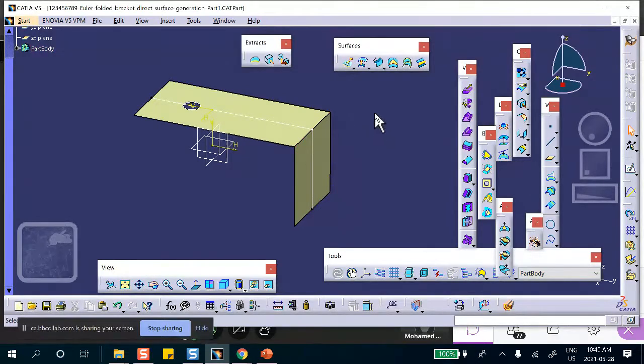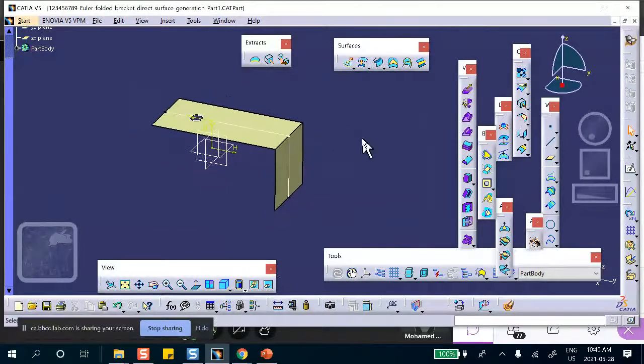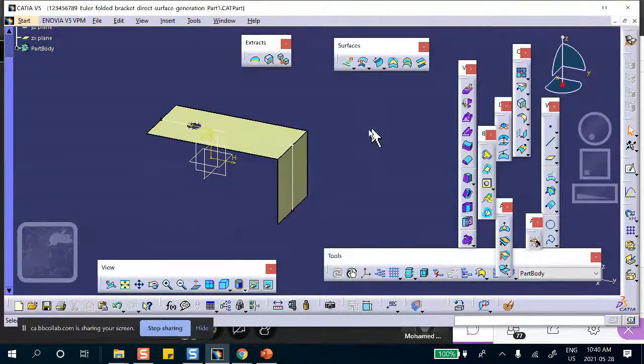All right, and this will save us in a sense, because when you mesh this piece right now, you get the same node numbers on the left side and on the right side of the seam. But if these are not joined, you get different node numbers here, different node numbers there. They may not even match at the location, and then you have to do some extra work. We'll talk about it later.